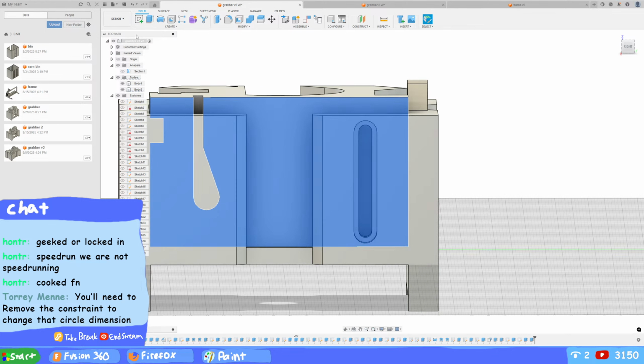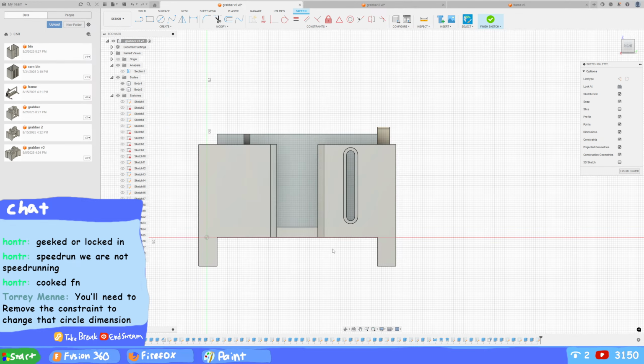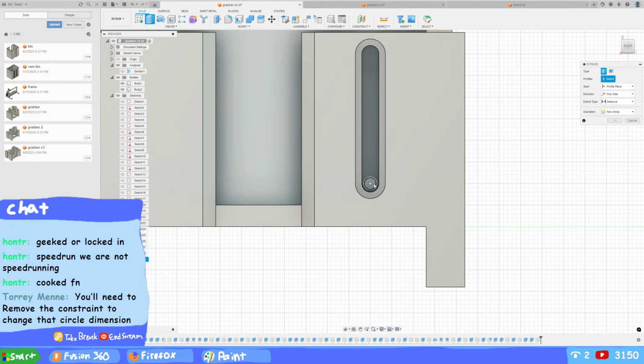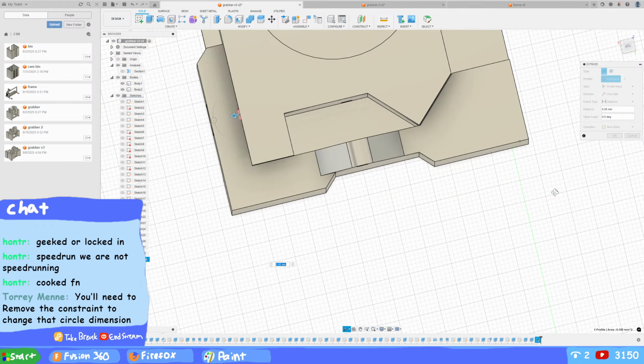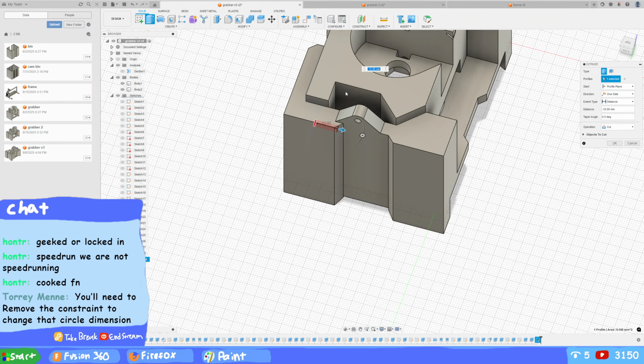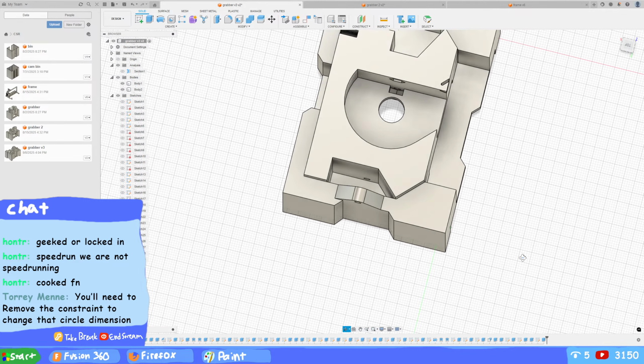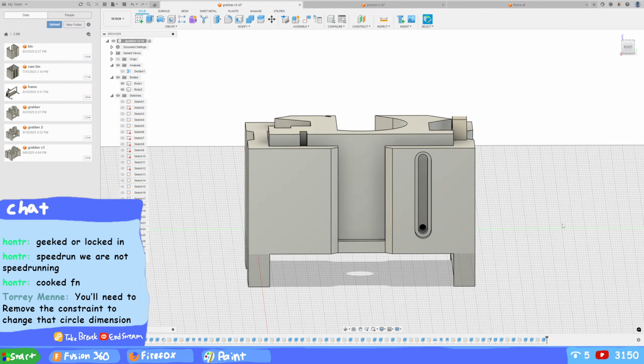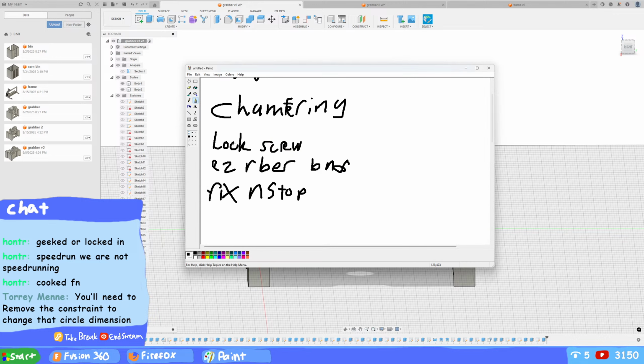I don't need to see this anymore. Create a circle at this point. Make this be 2.8. Finish the sketch. Extrude this one in some amount. -10? Sure, -10. Whatever, that'll do. Okay, great. We've got our slot now. We can check something off the board.